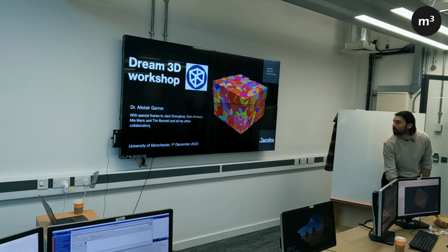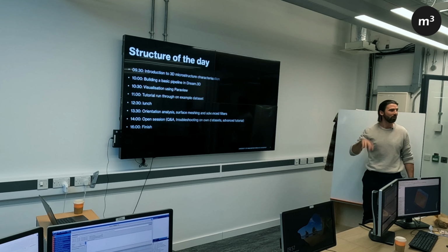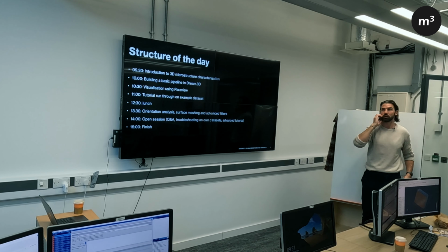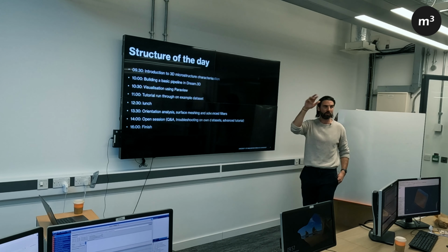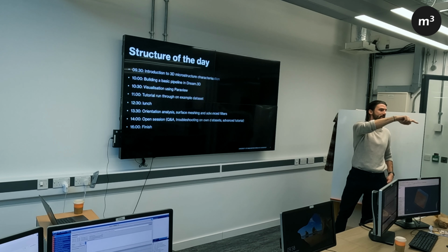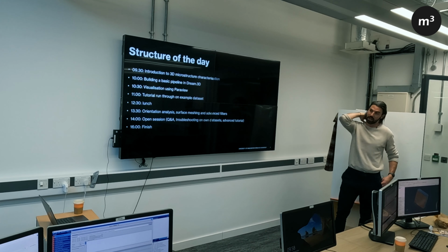But yeah, so welcome. So today the structure is going to be, this has already gone out the window, which is good. So yeah, I'm going to give a brief intro to why we do 3D microstructure characterization first. Then I'm going to talk through how you build a pipeline in Dream 3D. And then I'm going to show you some visualization using ParaView on the screen here. And then we've got some practice data sets on your machines. And then we're going to run through some of the basic pipelines, and you can have a play around with ParaView yourselves and have a little play with the data set there.